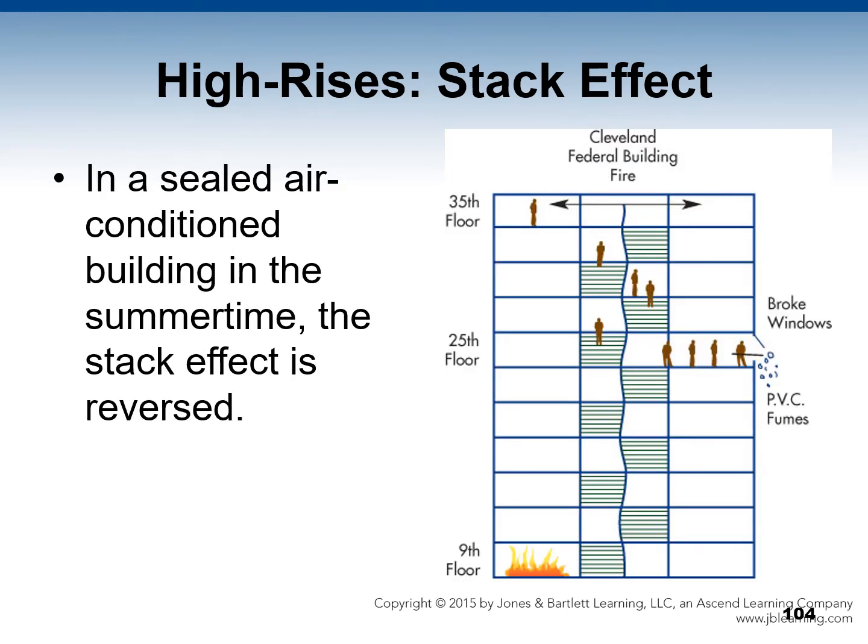Smoke that has lost much of its thermal energy can be delivered to upper floors by the stack effect. One example is a fire that vividly demonstrated winter stack effect, and this occurred in a federal office building under construction in Cleveland, Ohio. The fire was in a pile of rubbish on the 9th floor. Fumes from degraded and burning plastics traveled to the top floor by the stack effect.